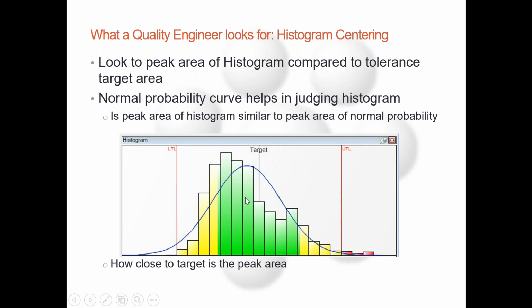And you can see some of this because this one falls off in this direction, while this is a steeper curve down here. Chances are very good that this is more like what you would see, where you're going to have some out of tolerance pieces at both ends, and this is probably as best tuned as you can make this particular process to fit the tolerance limits.